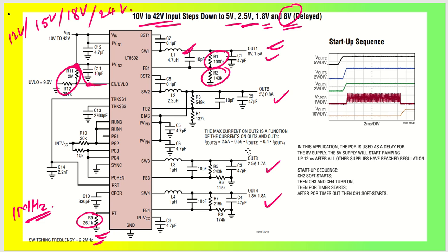Okay, good. So if you do have any questions regarding this, like how we can design our power supply system, this is a very good IC, quad input quad output step down regulator. So this is the reason I am stressing this particular IC a lot, and this IC has been used in many of our automotive applications, as well as many industrial cluster designs.